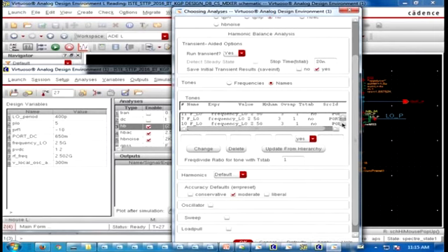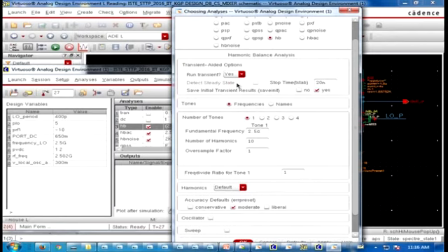It is just a list of things; it will automatically make a small table and ask me which band I want to select. So I have to select this, or I can select a set of bands and then tell it to run. But I will go for the frequencies because in this particular harmonic balance I will not calculate any kind of noise or intermodulation product.